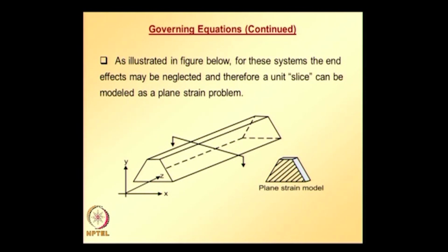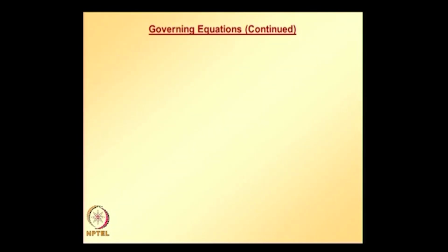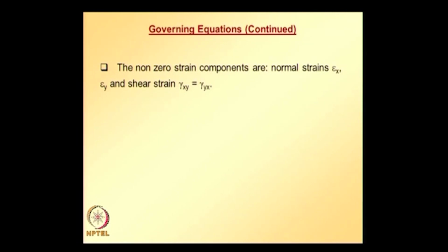Actually, this is a 3-dimensional problem, but for computational simplification we are taking it as a plane strain model, since one of the dimensions is much longer than the other dimensions. The non-zero strain components are normal strains and shear strain.